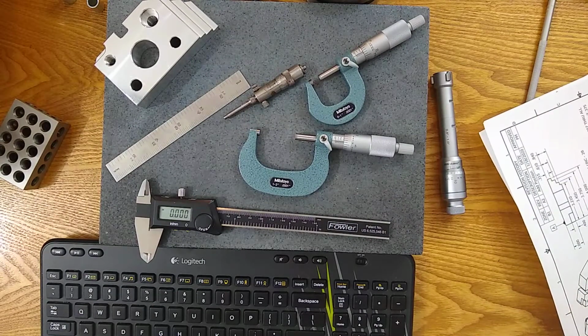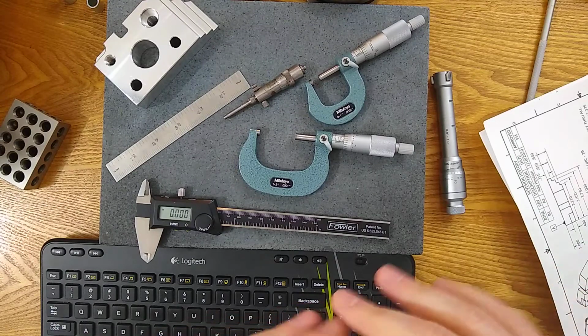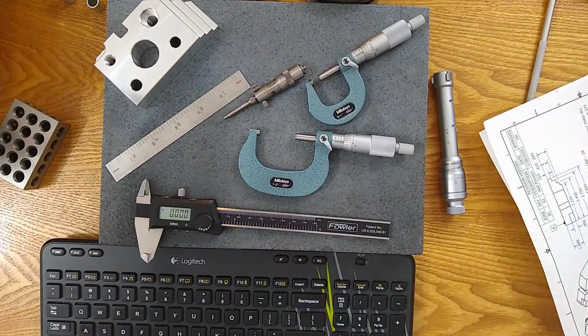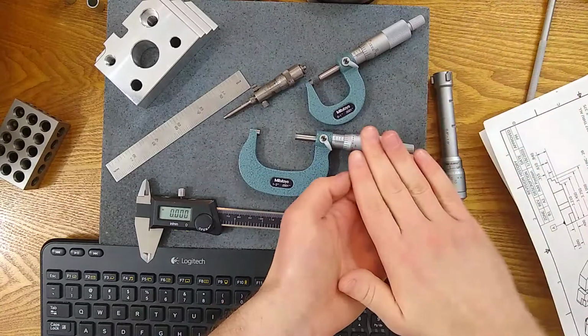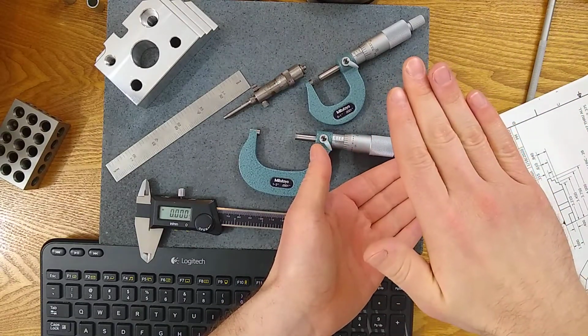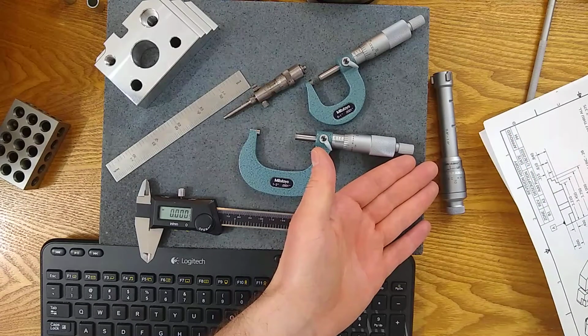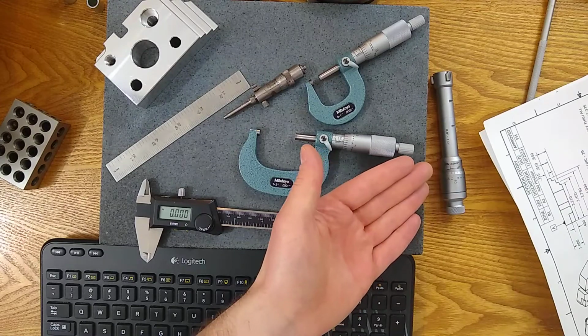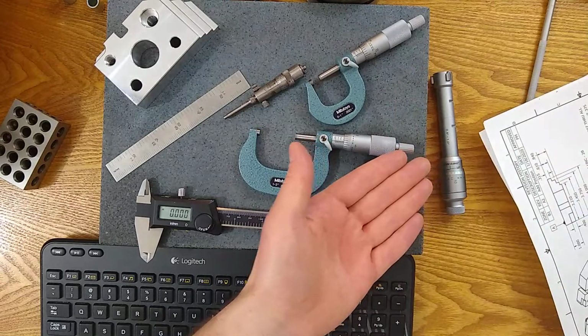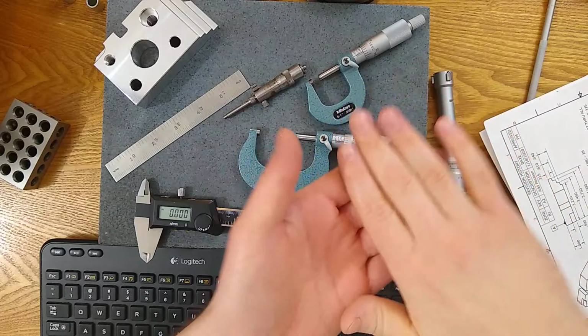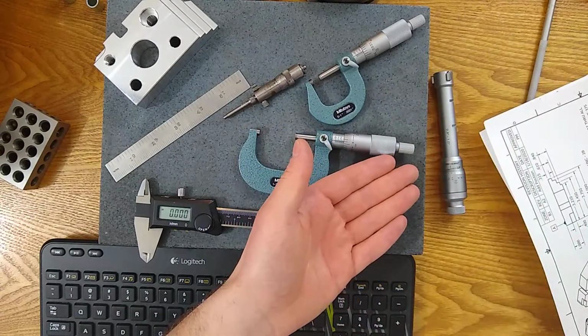I have a note on the bottom here. Height gauge and indicator accuracy is also length dependent, and the chart is not accounting for that. So CMMs, height gauges, anything that travels a large distance, there will be an accuracy error if you move a couple of inches, and there will be a bigger error added if you go a large distance. So height gauges are one of those tools that travel a long distance. Drop indicators can get 2-3 inches in stroke.